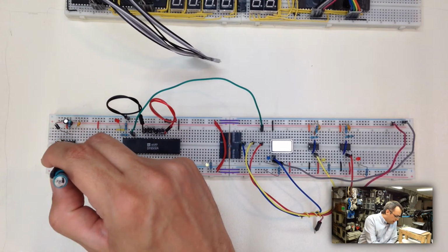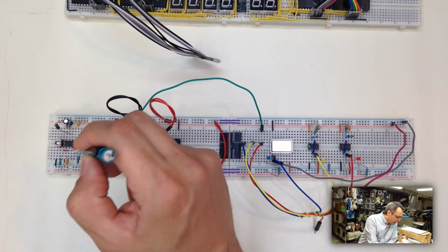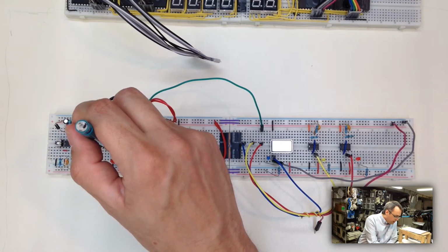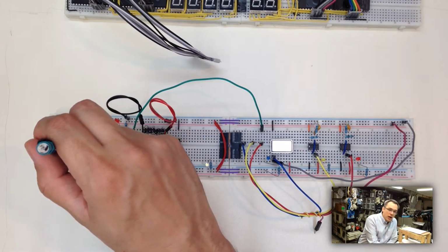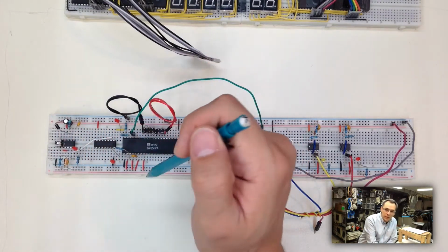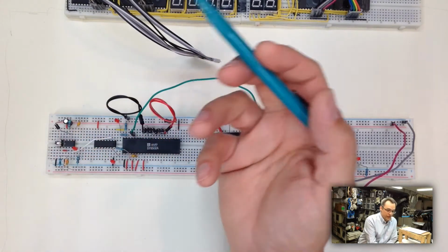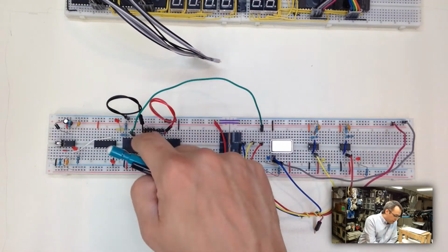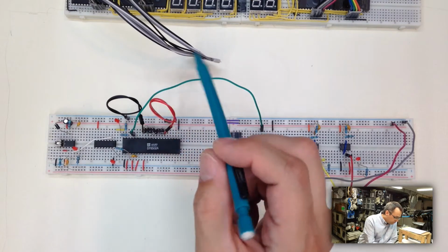Basically, that comes out of this pin, pin 3, which is the output pin of the 555 timer, and comes into an inverter. What that does is it inverts the positive pulse coming out of the 555 into a negative pulse, which is what the reset pin on the 6502 and all of the 6502 standard circuitry requires, and which will then reset the system.